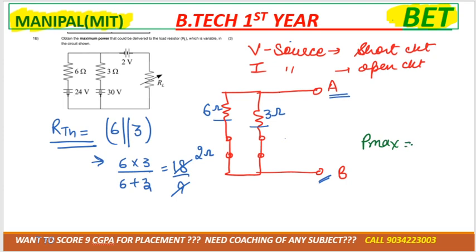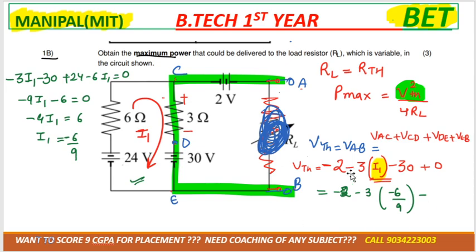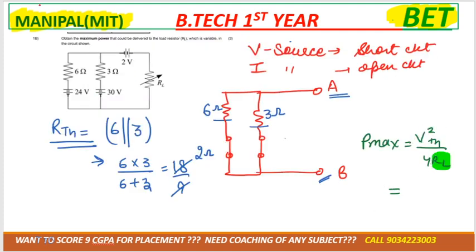So the P max formula is V_TH squared divided by 4 R_L. R_L you calculated, that is 2 ohm. V_TH you have calculated from here, whatever value you get. Solve it and then substitute it over here. Then after solving you will get the maximum power.